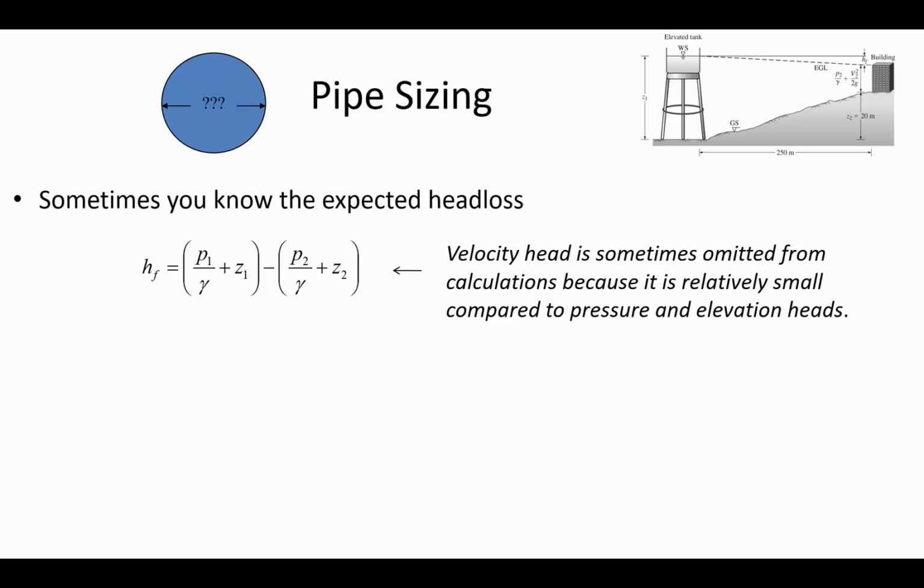You'd make every single pipe going into every home a meter in diameter, and then there'd essentially be no head losses because head losses are largely dependent on the flow velocity. But of course, that's a strange world that we won't even contemplate any further because the reality of hydraulic design is that we do care about cost, and we're always trying to find what's the smallest pipe size that's going to work for a particular situation.